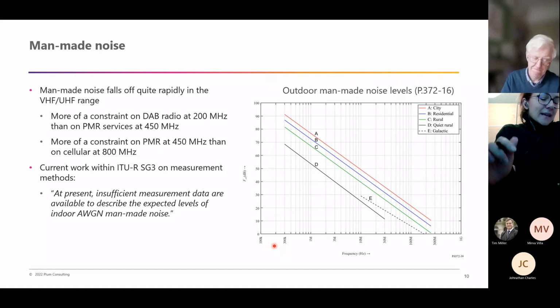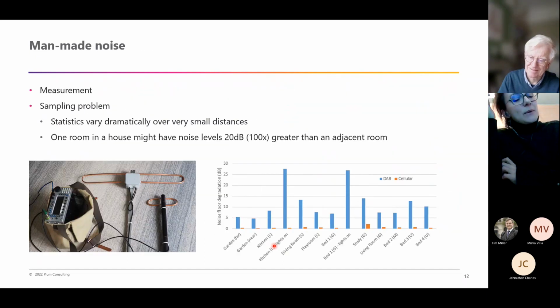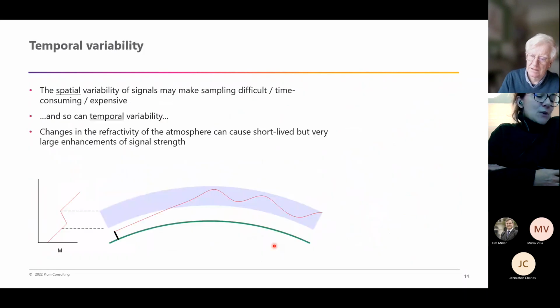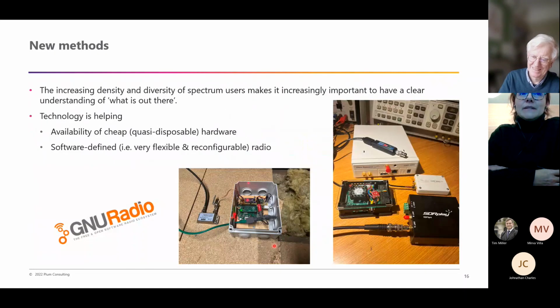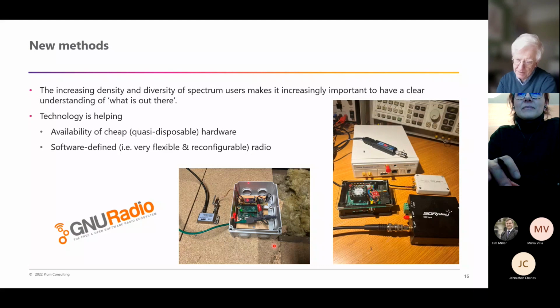Okay. Does the monitoring equipment itself sometimes cause interference in certain bands? It does. It's something we've had issues with, and it can be extremely embarrassing to be seeing a lot of interference and be hunting everywhere for the cause of the interference, only to discover that it is in fact the laptop computer that you're using to drive your logging equipment that's causing the interference.